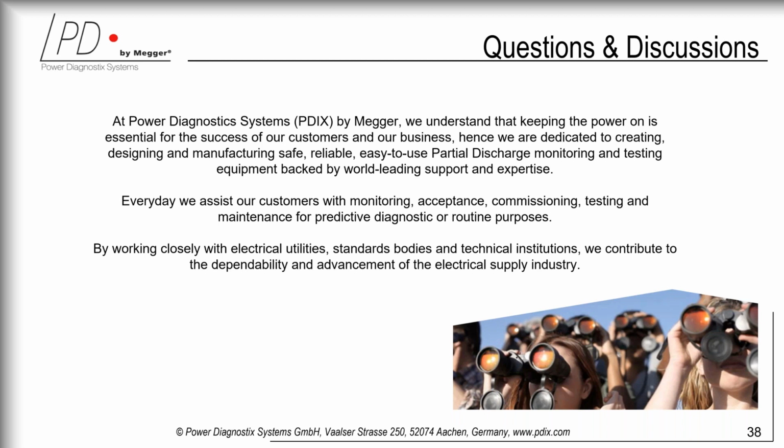Yes, for sure. So we have two outputs. From the bushing couplers, it goes into an adapter with one Teflon lead. And from there, we have two BNC connectors, and one is used for PD measurements, and the other exactly for tan delta capacitance. We have some customers who combined our PD measurement with a tan delta device from a different brand.